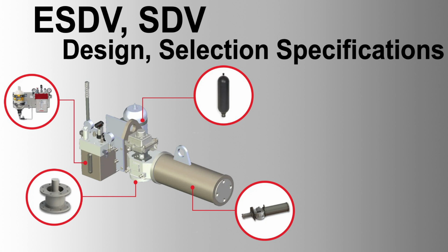Hand wheels, operating torque: not to exceed 80 Nm. Type: yoke-mounted, non-declutchable except for butterfly valves, which should be shaft-mounted. Pressure gauges, specifications: stainless steel case, Monel Bourdon, 6 inch dial, NACE compliant, plus or minus 2% accuracy at half range, glycerine filled. Process connection: 1/2 inch NPT-M, bottom. Local position indicator, type: mechanical, robust, beacon preferred.